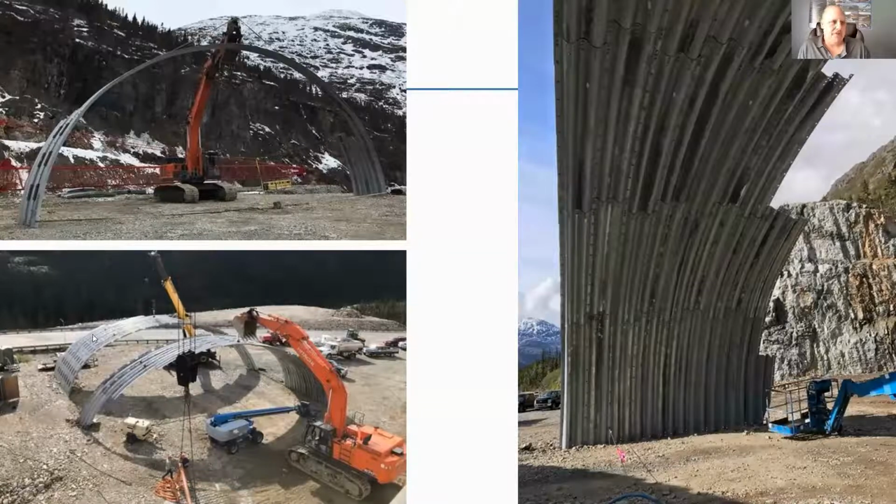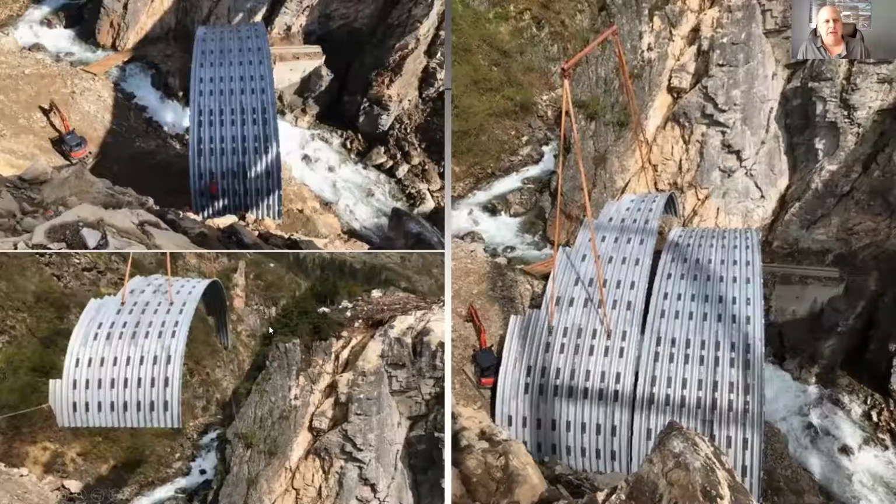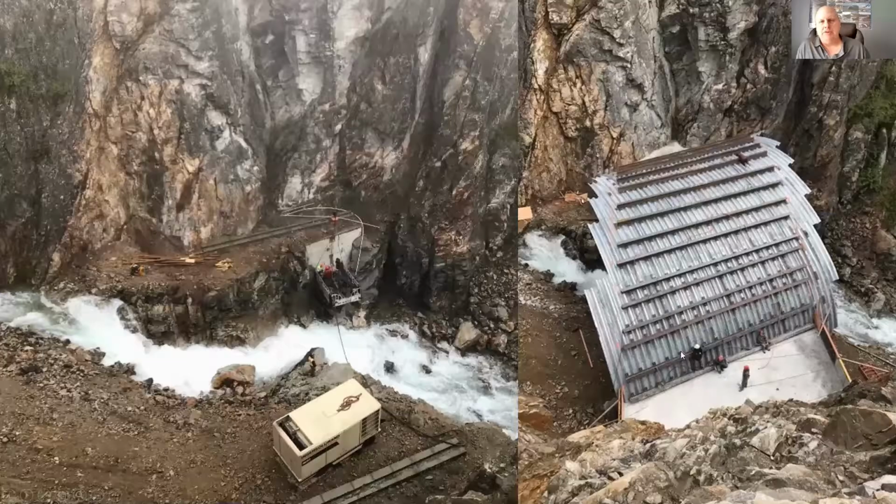Build the modules. Between each module, you put the pieces next to each other to make sure they're going to match up. In this case, they did it right up on top next to the existing bridge. So they just picked it up with a crane and lowered it right onto the footing. After it was in place, they installed the beams on the outside to support the skewed ends. We left the ends long or untrimmed here so they could set up their formwork, as they basically slip formed the structure as they placed the roller compacted concrete.